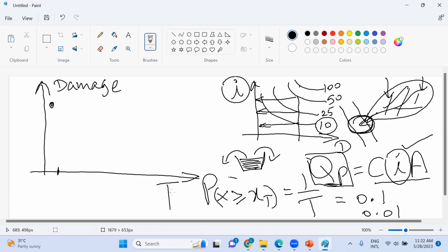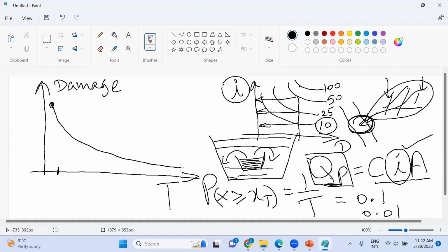But if you are increasing the return period, you are talking about larger rainfall intensity, larger peak flow, so now you need a larger cross section like this, so that the damage is now becoming smaller. Right? So it is always better if you can use a larger return period in your design.